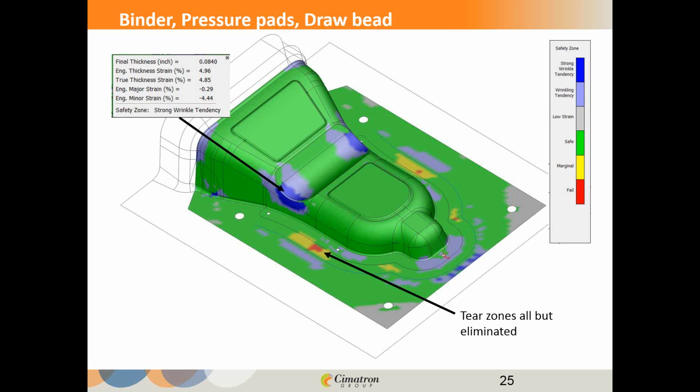However, if you noted, there's a key factor to this design that has not been included yet, and that's the pilots. Clearly, the part is intended to be formed by dropping it down on the die with the pilots locating and somewhat holding it, and then it's formed. Those pilots are going to greatly reduce the amount of flow that the material would have in those areas.